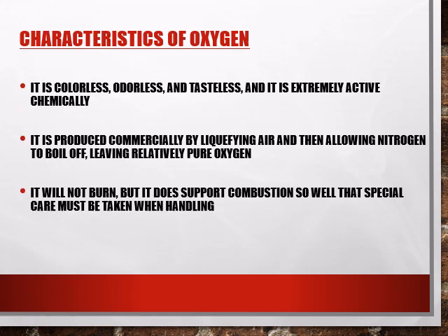Oxygen is a colorless, tasteless, and odorless gas. It's chemically reactive and supports combustion, meaning it doesn't burn on its own but can greatly intensify fire. Commercially, oxygen is extracted by liquefying air and allowing the nitrogen to boil off. It should not be used anywhere there is any fire, hot material, or petroleum products. If pure oxygen is allowed to come in contact with oil, grease, or any other petroleum product, it will combine violently and generate enough heat to ignite the material.